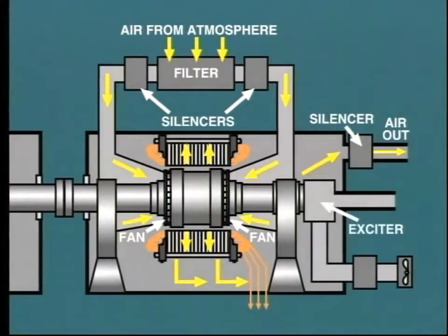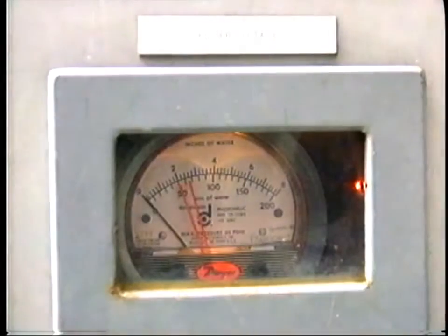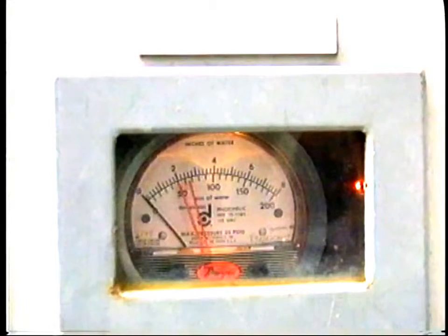Usually, a separate cooling system is provided for the exciter or collector rings. In this particular arrangement, a small fan impeller is fitted into the collector air inlet adjacent to the collector rings. Air is pulled in through a filter to circulate through the terminal connections and collector rings. As we can see, this system is self-contained and requires no attention from the operator other than to ensure that the filters are clean, thus allowing sufficient air to pass. The pressure drop across the filter will indicate when it needs to be replaced.